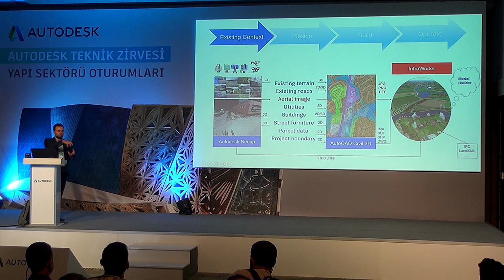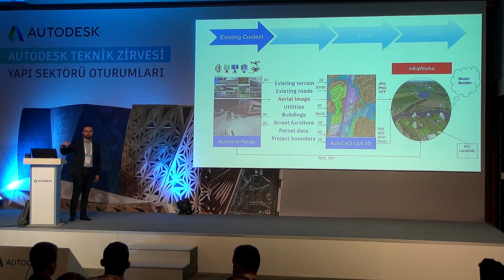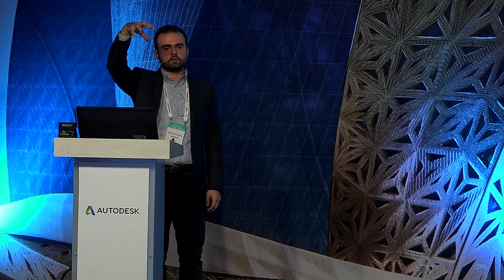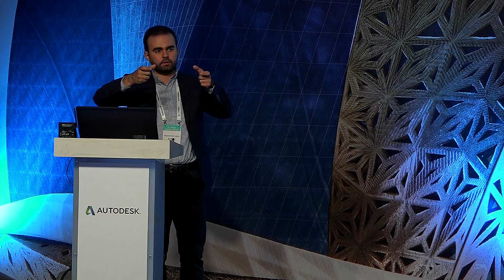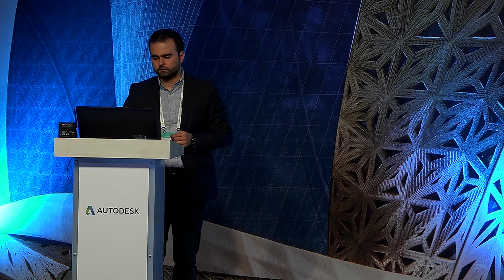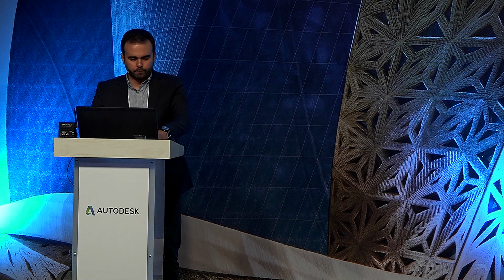It can be taken by a laser scanner that is fixed, or we can put it on a vehicle that goes around the site and scans everything, or even we can fly a drone, and that drone has a camera, takes pictures, and from those pictures we create a 3D model. That's very quickly what point clouds or laser scanning is.